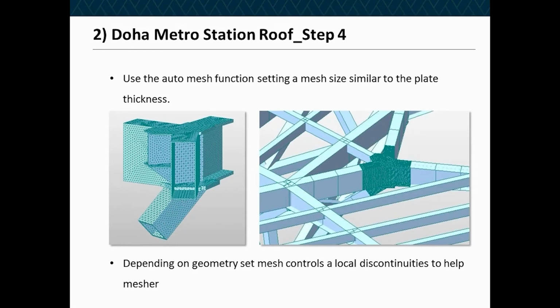And it really is. I mean, it's complicated the first time you do it, but trust me, if you get into the routine, you know what to look for, you don't fall into the traps, it's fine. We find it incredibly powerful for overcoming very complex connections where you really want to be sure that you're not overstressing some part of the connection, and you want to avoid the complexity of trying to establish the correct boundary condition. Because of course you could analyze this within FEA, and FEA is fabulous at analyzing things. But you'd have to generate exactly the right stiffness of boundary condition on each of these corners, or each of the faces.